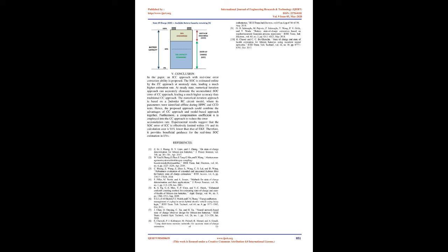Figure 1 shows the flowchart of the enhanced Coulomb counting algorithm. At the start, the historic data of the used battery is retrieved from the associated memory. Without any information for a newly used battery, the SOH is assumed to be healthy and has a value of 100%, and the SOC is initially estimated by testing either the open circuit voltage, or the loaded voltage depending on the starting conditions. The estimation process is based on monitoring the battery voltage, VB, and IB.